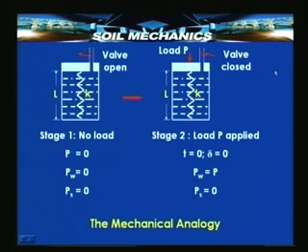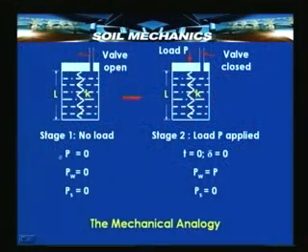Whatever I have explained briefly is illustrated in this slide. Stage 1 is the initial stage, with no load. The valve is open, but there is no flow, the water is in equilibrium and only hydrostatic pressure acts. The applied load P is 0. The load transferred to the water is also 0 because no water has been expelled, and the load transferred to the solid grains is also 0. So external load has not been applied, and it is a completely free system.